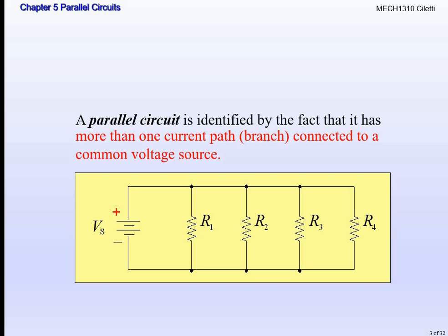So in a parallel circuit, you will have multiple different currents, and the currents will vary. Versus the series circuit we talked about last chapter, there was only one current and one path. A parallel circuit has multiple currents and multiple paths, multiple being more than one path in general. So this one has 1, 2, 3, 4 different paths that it can take. And there still is an I total as well when we're talking about current.